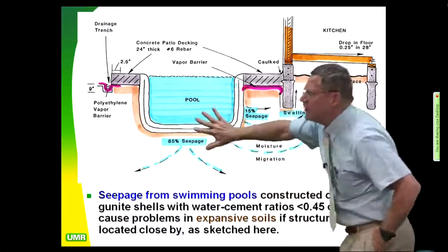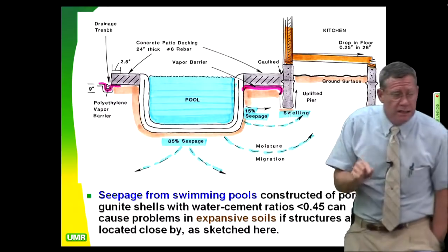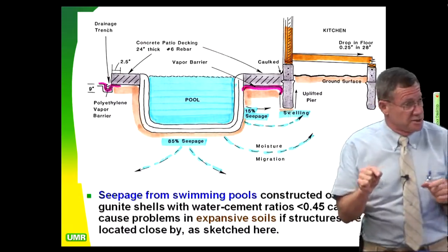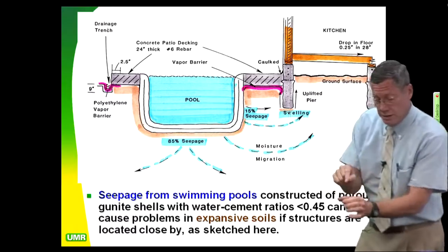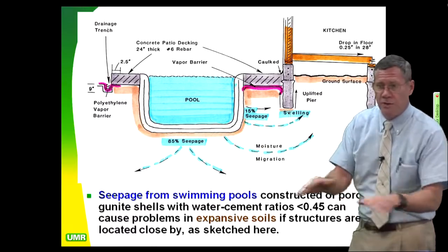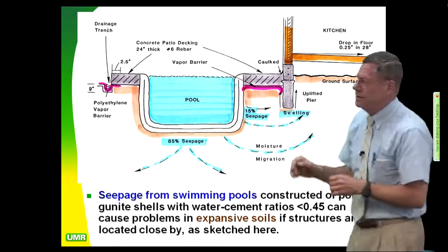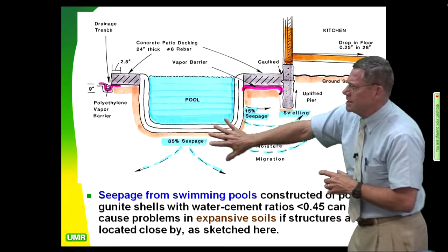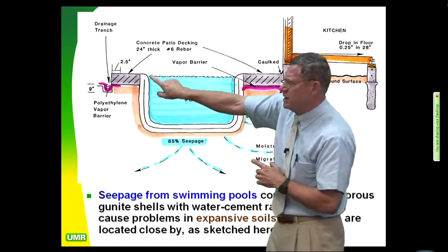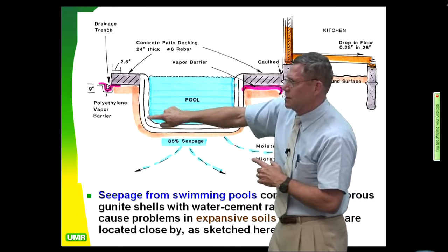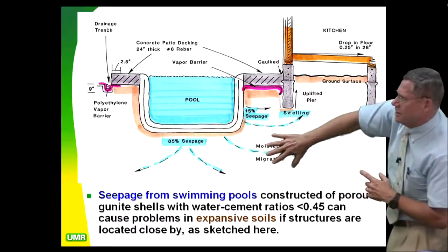And so this has nothing to do with hydraulic conductivity. You hear that? Hydraulic conductivity has to do with saturated conditions. This is unsaturated soil mechanics. And this goes very fast. This is like watching a pipe break in a dry fill. You can just watch that thing moving every minute, very, very rapidly. It's chemically adsorbed. And so this thing is spreading out, and you get about 15%, or 7.5% off each side, because you got diminishing hydraulic pressure as you come up, less and less water depth. And so you have some water coming out here, but not nearly as much as you have coming under here and coming up.